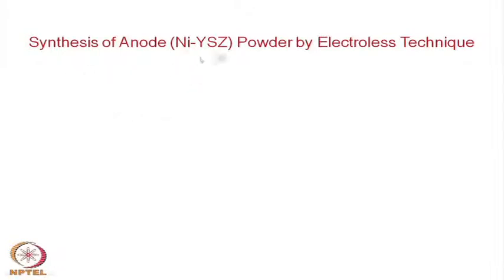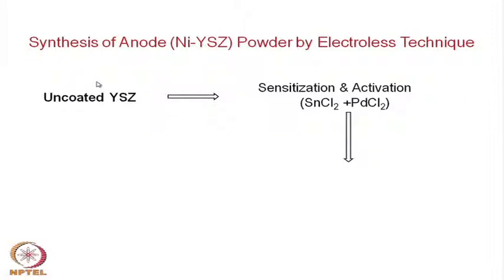Here a particular technique has been used, which we call the synthesis of anode powder by the electroless technique. Let me try to describe this process. This is a very simple process where each of the individual YSZ powders has been coated with metallic nickel.